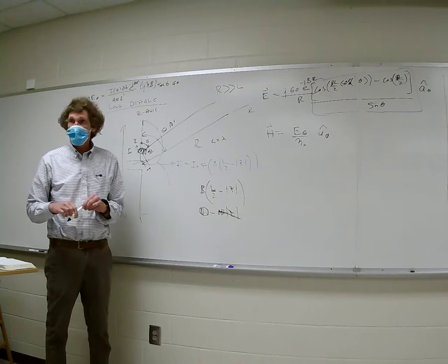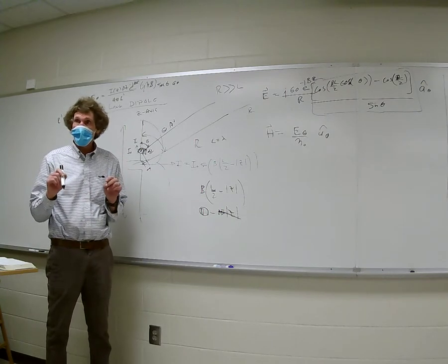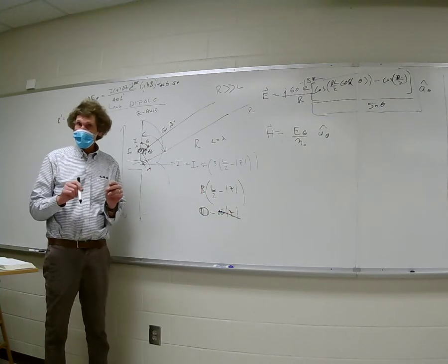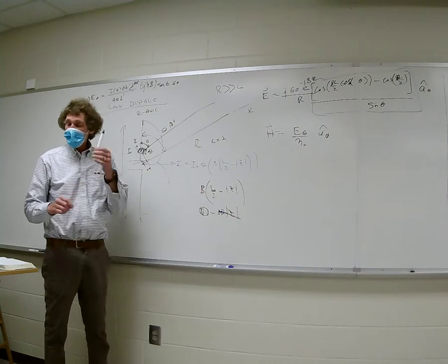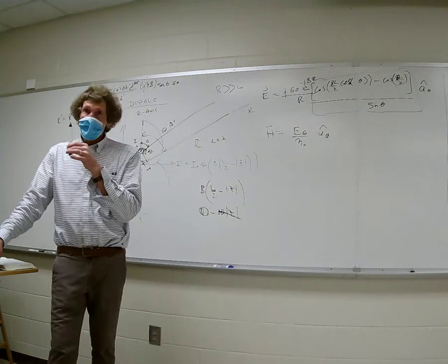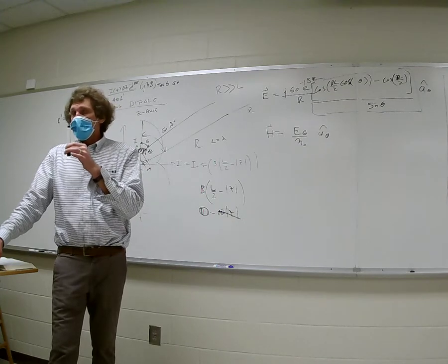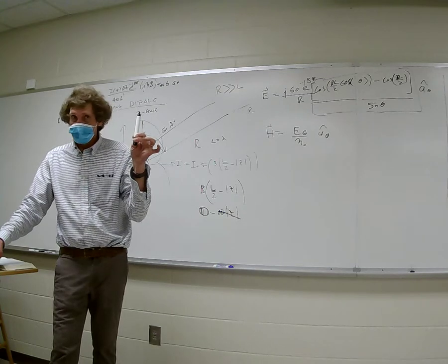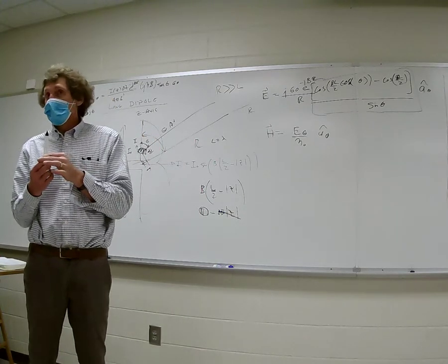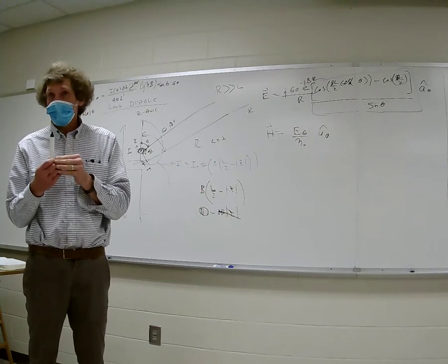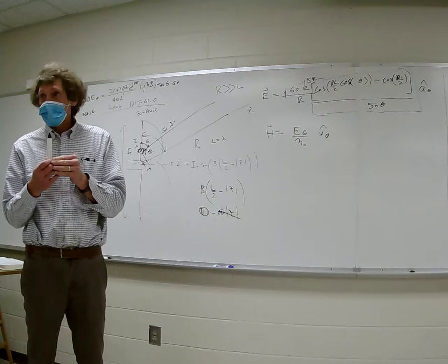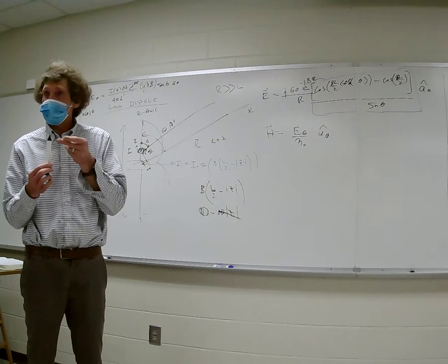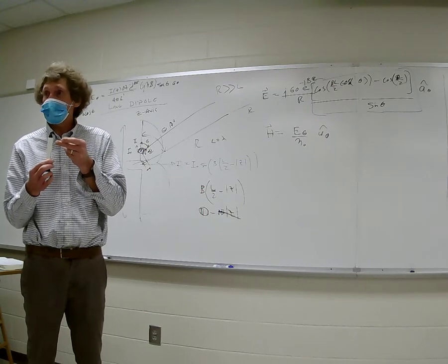And I posted some things about the current, both the real and imaginary part, for dipoles of arbitrary length. I've got to tell you one other thing, and it's not said in this book that way. Antennas don't have infinitesimally small diameters or radiuses. The actual driving point impedance of any kind of wire antenna is a function of the radius, and especially if the radius is of the order of 1/10 of a wavelength. Now, hear me on this one. You remember skin depth, right? Skin depth becomes a factor in the actual resistance, the actual heating of the antenna that would occur because of the resistance.